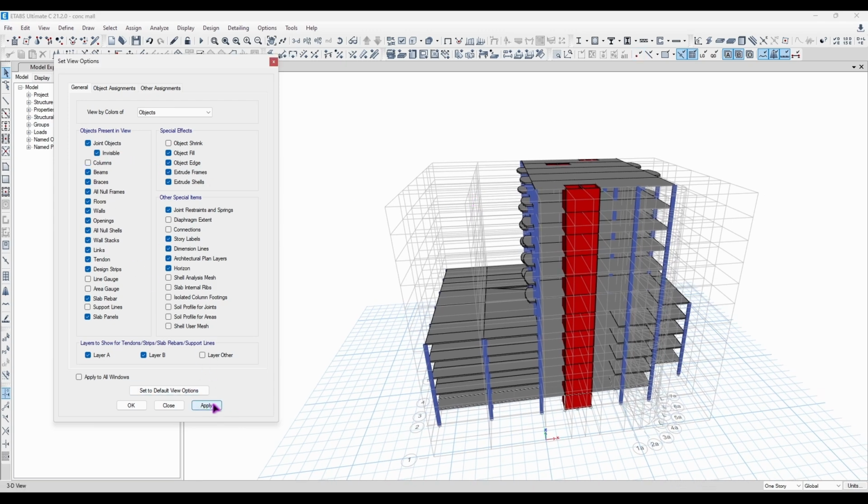And for the columns, you just technically set the display of the columns. Now I remove the columns. Beams, I don't have beams on this since it's a flat slab with shear wall, so it's not going to show anything. There you go. And braces, which in the bracing system, if you're working with steel structures, but I don't have any. Now null lines, we're going to go into the elements soon, so this is the visibility of the objects you have on your project.